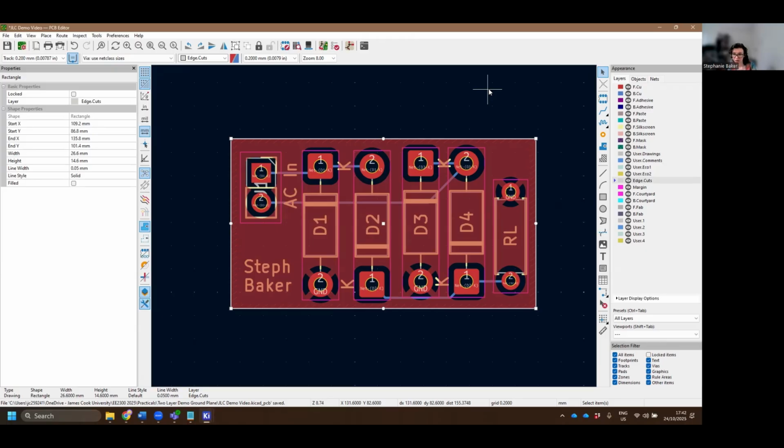will be able to route it in a few different ways, either 2-layer where you set your entire front and bottom as a ground plane, and then you have your routes carved out. Or if you only need to route on one side, using your other layer as a ground plane to create that really good signal integrity. So that's a really nice option that we've got.